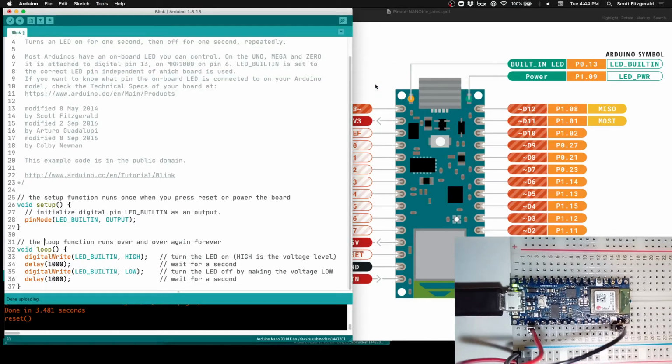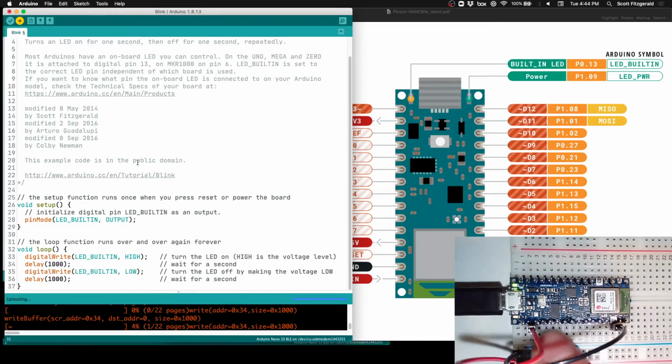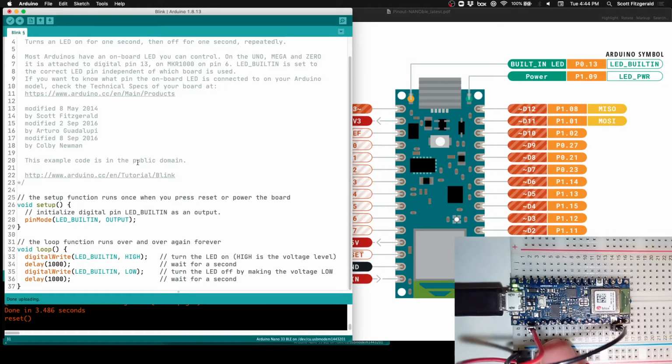So click on that, and once you have, you can check down here at the bottom where my mouse is moving around. You can see Arduino Nano 33 BLE on it. So this is the port and the board that I'm talking to. And to program it, I click on Upload, and we wait for a few moments. And you can see here this light is no longer flashing, but it's now sort of fading. It's breathing in and out. And now it has started to blink. So it's like just blinking on, off, on, off, on. So this is happening once every second.